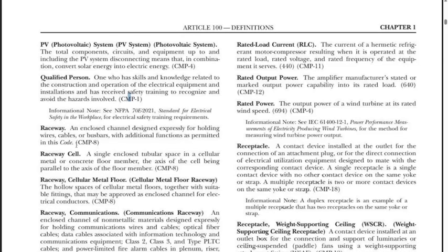Next one is right under that one, which is raceway. Raceway is going to come in a lot of different forms, from Romex that you're working with in code A to the conduits that you'll be bending in code D and also in code A with EMT. In code D, you might get into RMC. I think they're changing that around a little bit. But also the flexible, Romex, the ones we bend, EMT, things that have cables inside, wires inside, even bus bars, these larger pieces of metal that connect circuits together, those will be inside panels.